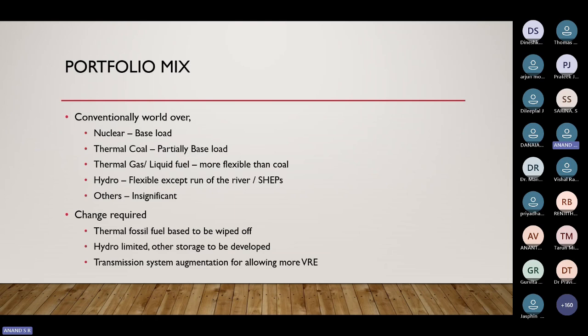One of the developments that has been done across the world, and we are also doing in the same way, is to duplicate the boilers. So if you duplicate the boilers, then if you want to reduce the generation, you can shut down a boiler as such. With the existing capacity in the case of coal-based generation, the possible reduction is almost up to 55%.